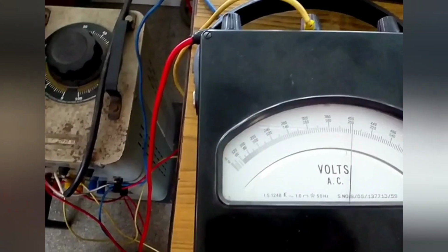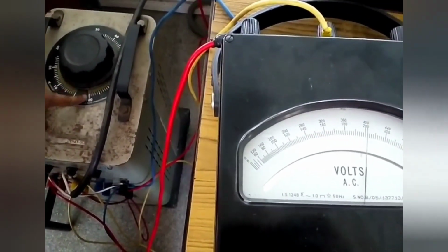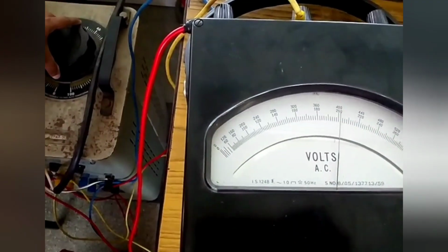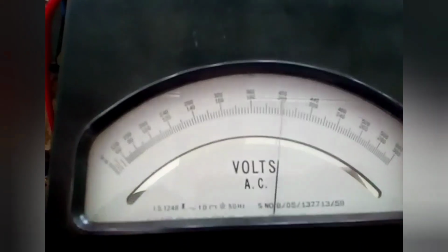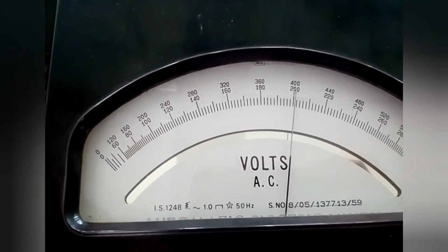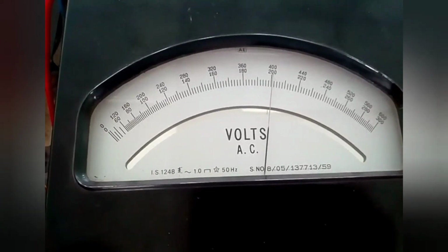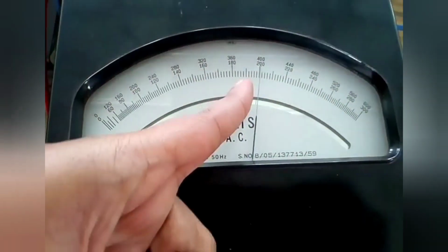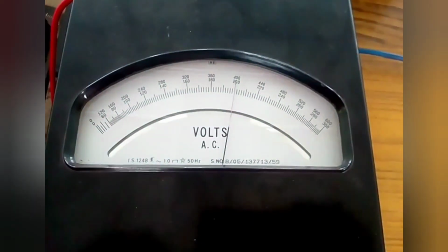Okay. So now we can observe that by increasing the three-phase auto transformer, I have set it to the maximum position like this. By setting it to maximum position, we can observe in the voltmeter, we are getting 400 volts as a maximum voltage. Maybe we have to get 440 volts, but for the maximum position in the auto transformer, we can get only up to 400 volts. So no problem. 400 volts is also a three-phase voltage. So plus or minus 20 volts tolerance will be there.